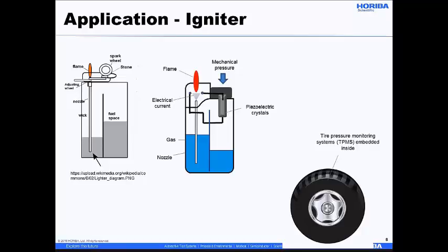So car manufacturers are now using piezoelectric crystal. When you attach this small, tiny sensor to the tire, it's going to constantly move, and that movement, that stress and stretch, will create a tiny bit of electricity, so it constantly gives feedback as long as you're driving, as long as the wheel is turning.